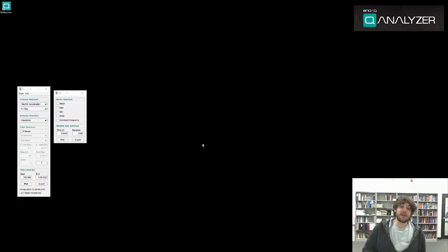The metric is whatever you've checked in the metric selection section. So for example, if I were to select mean, max, dominant frequency, it will perform a mean on each one of those sections, a max on each one of those sections, and will calculate the dominant frequency and amplitude of those sections. Each one of the non-overlapping sections will have this applied and then will be reduced to a single scalar value. The scalar values produced by these metrics will then be what are plotted.